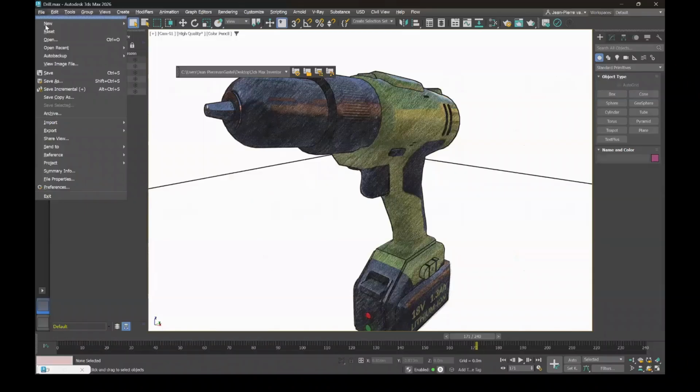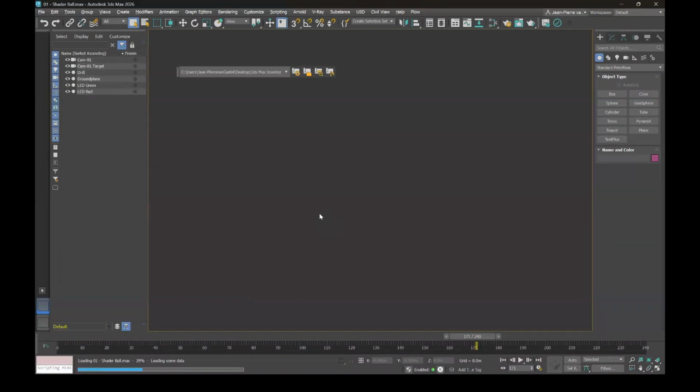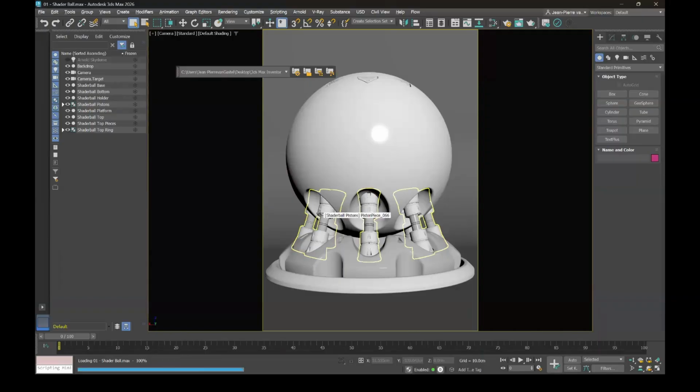So just let me open up my other scene, Open PBR, and I also need to closely watch the time because there's always so much to tell when it comes down to 3ds Max. So this is some kind of a photo studio I'm normally using when I create my materials. It's a spherical object, so it gives me the best quality when it comes to reflections, etc. I do have an environment, so the HDR, the 360-degree environment. And when I'm satisfied with the material, I store it in the material library, so I can always reuse the material.